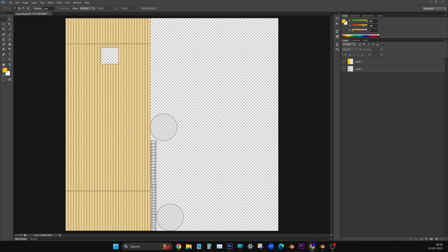So now you have to select another layer, you have to create it in the layer box. So this is layer 3. Layer 1 should always be there. Now here you are going to choose another same color, but draw a different rectangle, mark rectangle, for the second rectangular piece.